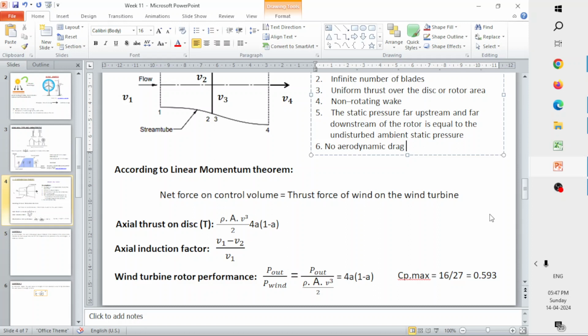So those minor losses from the different parts in your windmill, and the different types of losses due to the wake formation, blades, and the drag, your performance, or the amount of energy that you can harness from the wind, will decrease substantially, and the value will be somewhere around 30 to 40%, or you can say 30-35% only. It won't be 59% as what you actually saw.